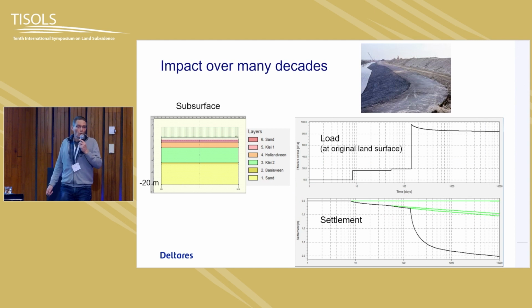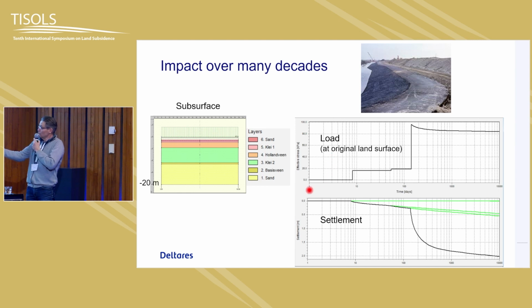Well, we do a lot of modeling engineering. In this university, a lot of students are very familiar with this, and we're using software like this, building subsurface strata with properties and loading. These are, let's say, loading steps on a log time scale. This is 30 years, typically what is calculated in predictive settlement modeling. And then you predict a settlement history over time. And you see here the stepwise settlement.